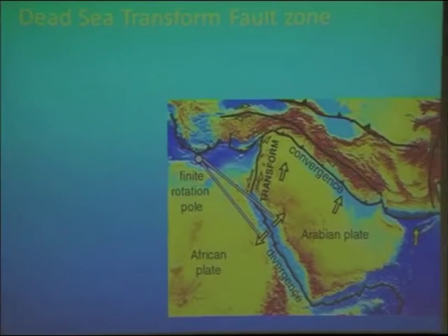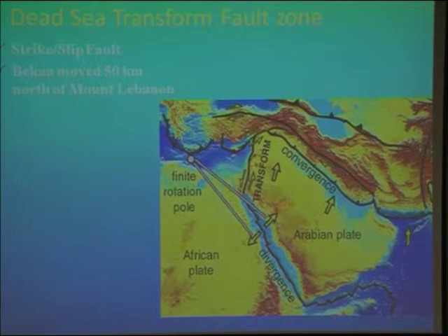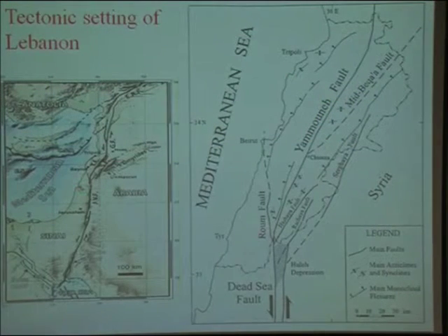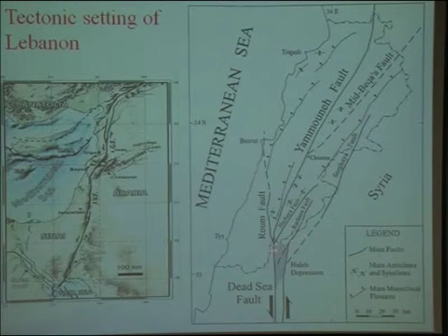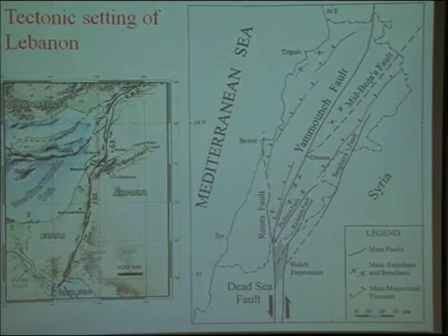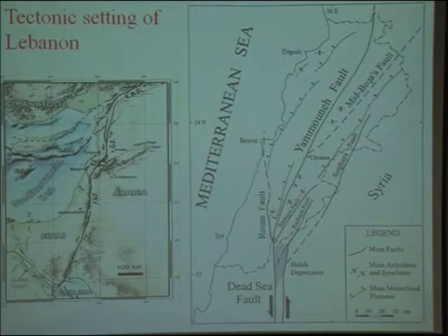As you can see, the fault that I'm talking about is a plate boundary between the Arabian plate and the African plate. And whenever there is a plate boundary, it means there are earthquakes. When this major fault enters Lebanon from the Galilee heights in southern Lebanon, it forks out into several faults: the Roum fault, the main Yammouneh fault, Rashaya, Hasbaya, Serghaya, and others. All of these trigger earthquakes.